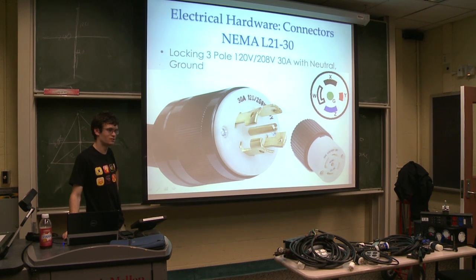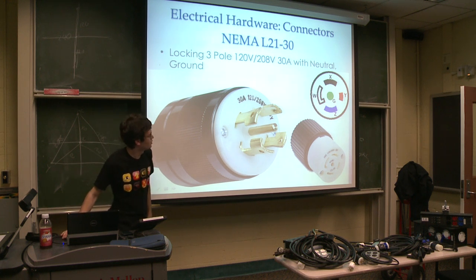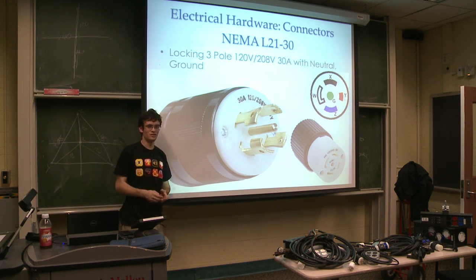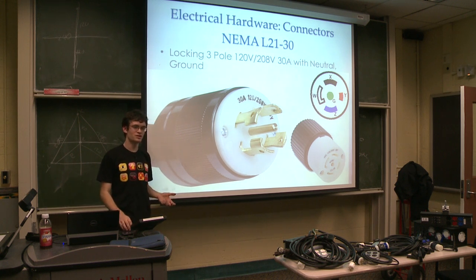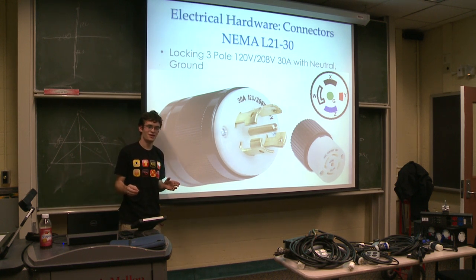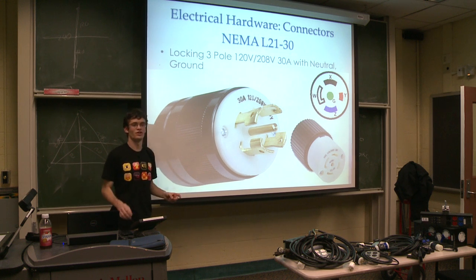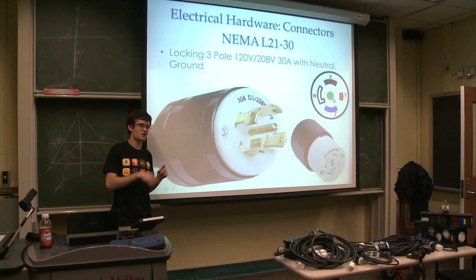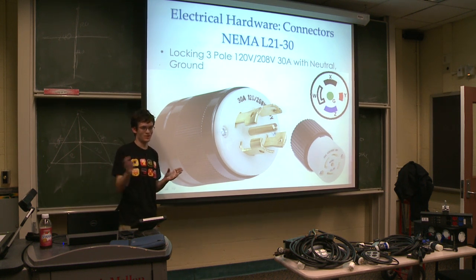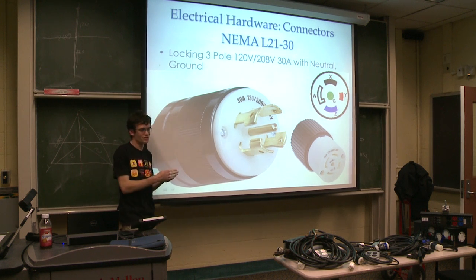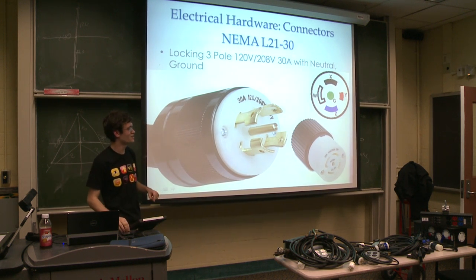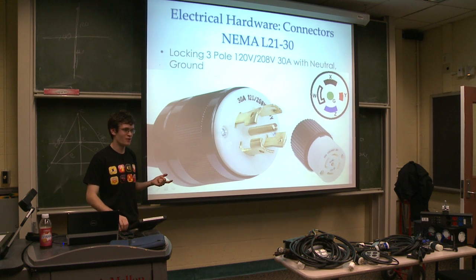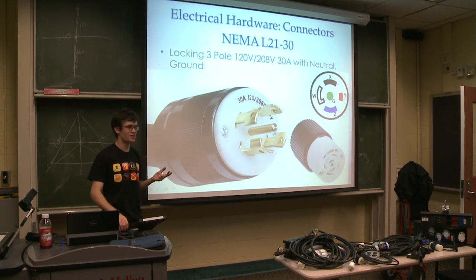There's one other thing you can sometimes run into when you get six Camlock connectors: double neutral. I mentioned earlier that inductive loads are difficult to do math with because they shift the current in time relative to the voltage. An effect of that is, instead of the phases balancing each other out, as usually happens with resistive loads, you can have multiple phases worth of current all going through the neutral at once, not balancing out through the other hots. So sometimes on dimmer racks, you get two neutrals to carry the additional load.